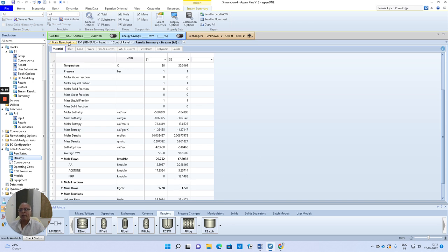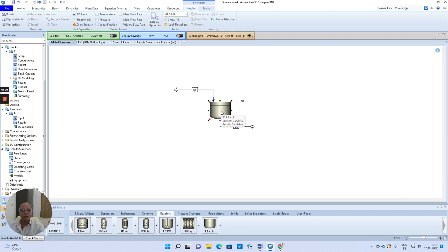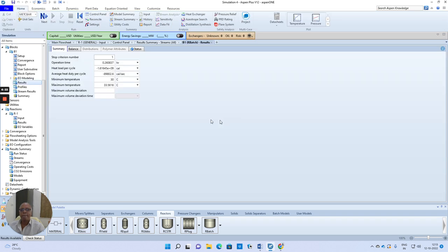Now, what about the time required for achieving this conversion? So this is the amount of time that we are required to proceed in order to obtain 98% conversion with respect to this reaction. Of course, you can easily check analytically whether this time that has been calculated by the simulator is matching with your analytical result.